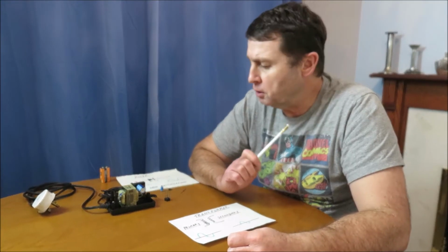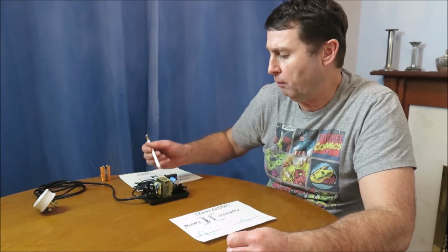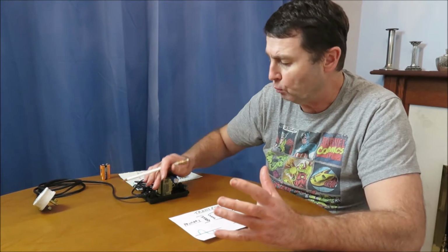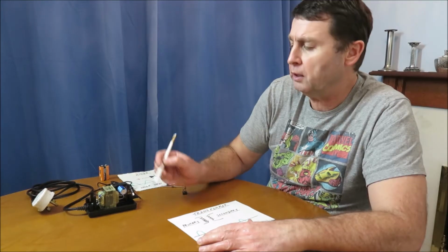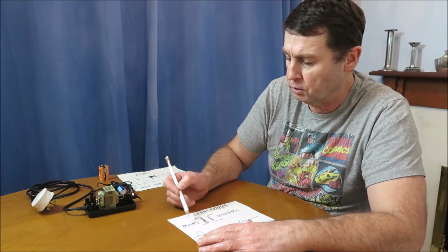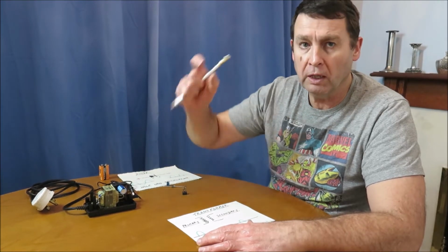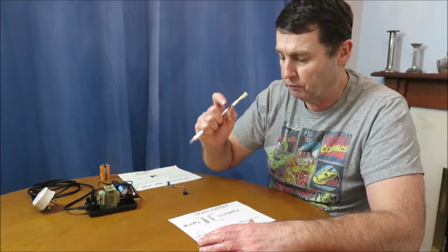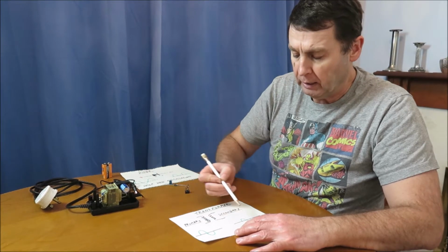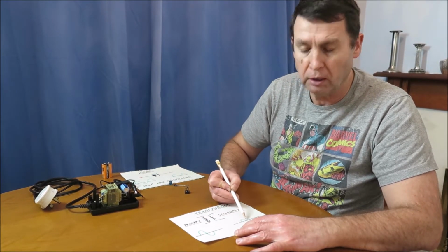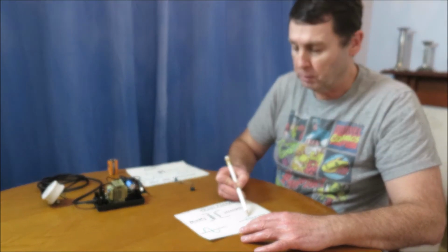Okay, so let's have a look at each of these components in the power supply individually. First of all, we have the transformer in there, which is our step down from the mains voltage. So if we have a look at it, we've got 2 windings on our transformer. Primary, where our mains goes into at 230 volts, and our secondary, which will have fewer turns on it. So the amplitude of the voltage, or the height of the wave, if you like, will come down. So we can see a 230 volt sinusoidal wave going into the transformer there, and coming out the other side of the transformer, secondary, still a sinusoidal waveform. So the waveform's unchanged, but it's lower in amplitude, so the voltage is being decreased.